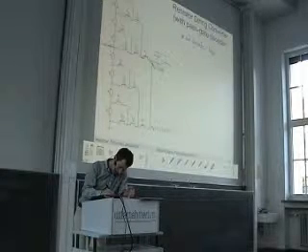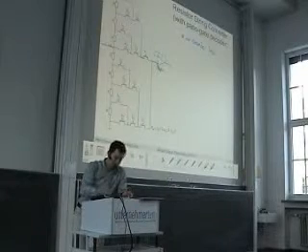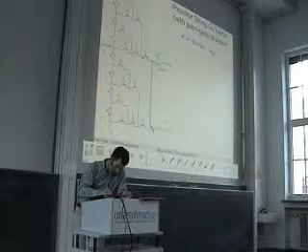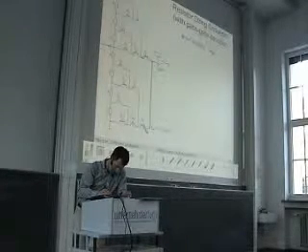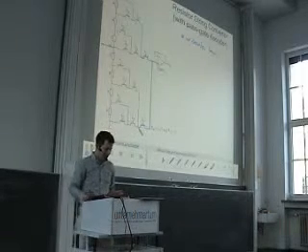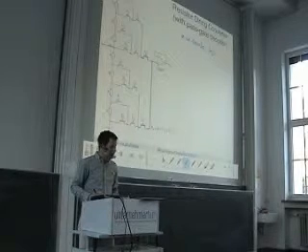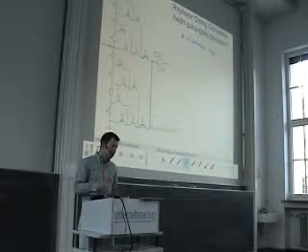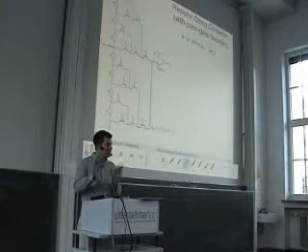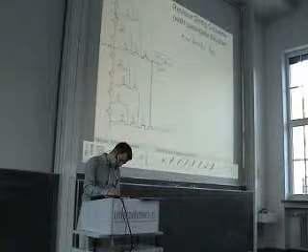So if the B1, the MSB, is high, we select the lower part of the tree, or if the B1 is low, then the B1 inverse is high and we enable the lower part of these voltages. Then we can use the second bit in order to search or select voltages in either the upper or the lower part. So the next voltage